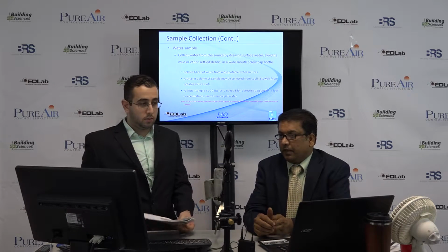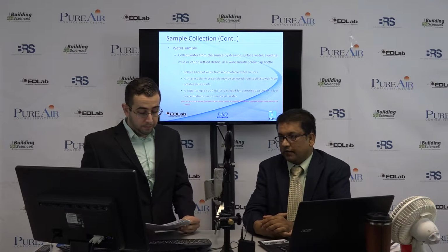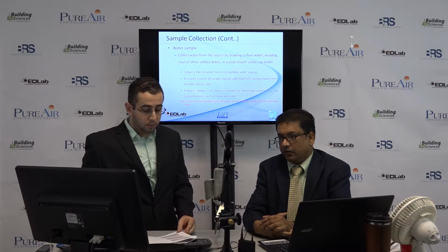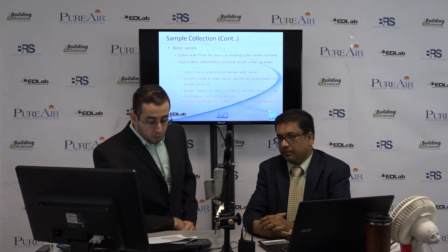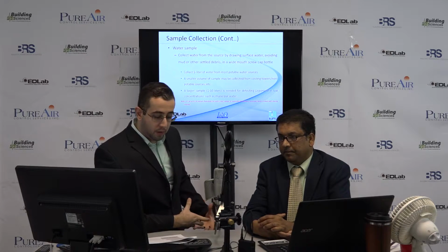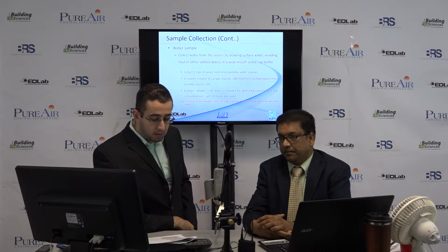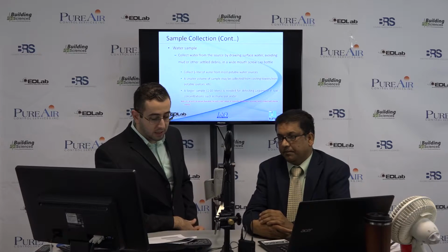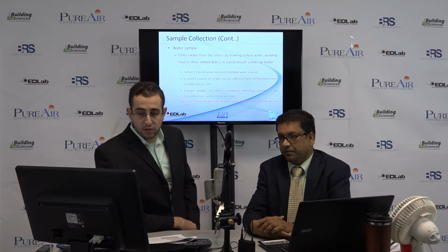Well, that's very good, but can you elaborate on how much water one should collect for testing Legionella and how they should be collecting those water samples? Of course, and this is important. Water is drawn from the surface of the source, and you want to try for the most part to avoid any other debris, something like mud or dirt or anything along those lines that could get in and affect the sample. You typically want just water when it comes to collecting Legionella. You want to collect 1 liter of water for most potable water sources.